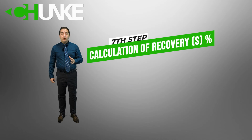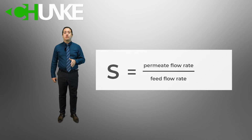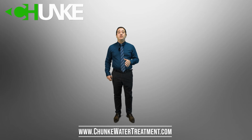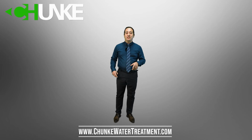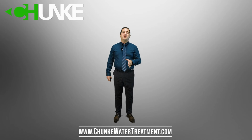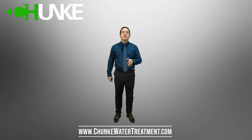Step 7. Calculation of recovery. Recovery is the ratio of permeate flow to feed water flow, calculated with this equation. With increased recovery, the pressure may increase somewhat, but the brine will be more concentrated, which can make disposal more difficult. Now it becomes the more technical part, maybe get a cup of coffee and focus on the details more, because it is a very important part. At Chunke, we design systems to get the best recovery rate with lower energy consumption and longer membrane life. It makes us different from other water treatment companies.